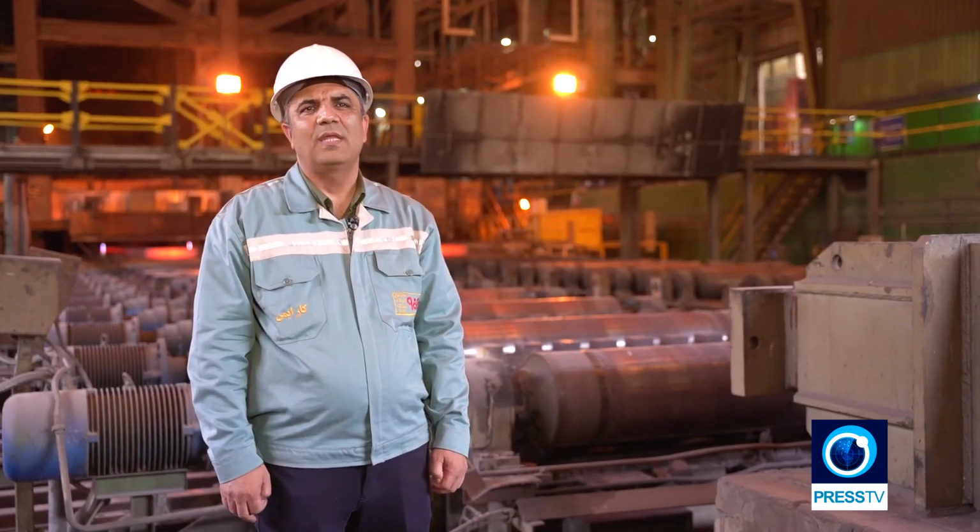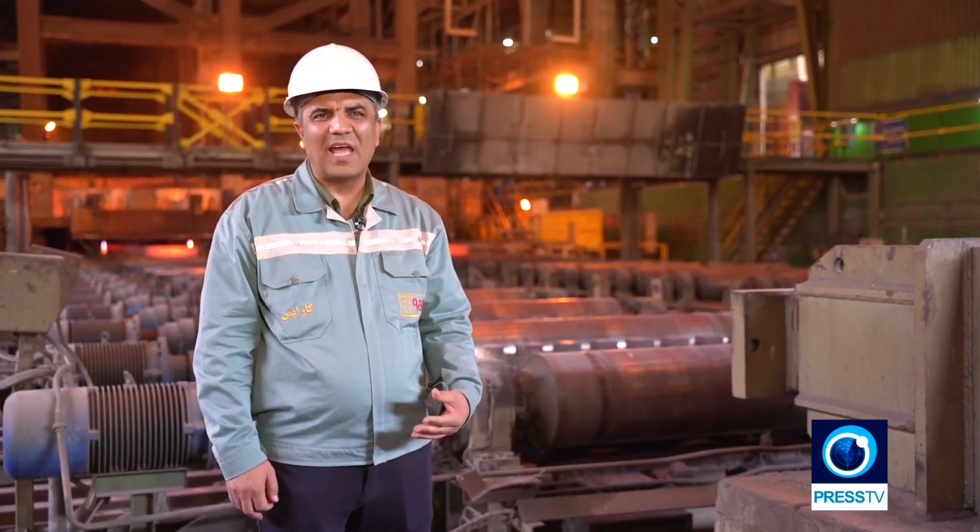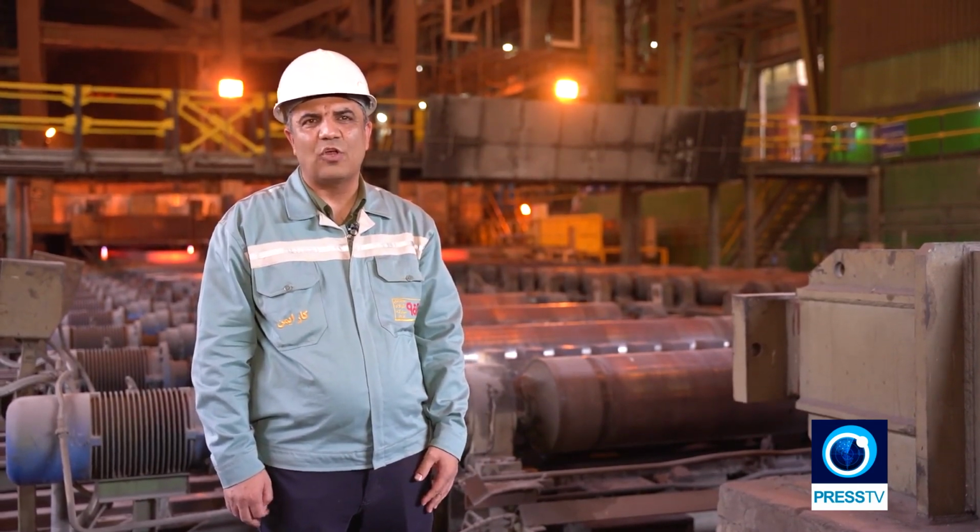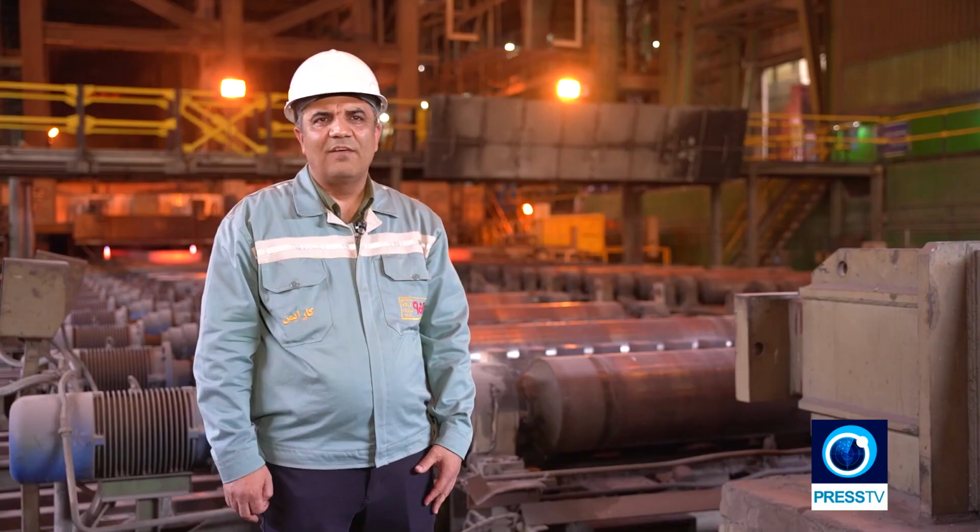In our steelmaking process for this specific grade, we implement strict control over raw materials entering the production units. For example, we carefully manage the furnace charge mix in the electric arc furnace, add specific alloys, and reduce sulfur content to below 50 ppm, specialized operation carried out in our ladle furnaces. Additionally, we lower the hydrogen content in the steel to less than 1.5 ppm using advanced degassing units, which we have established at Fouad Mobarakeh.